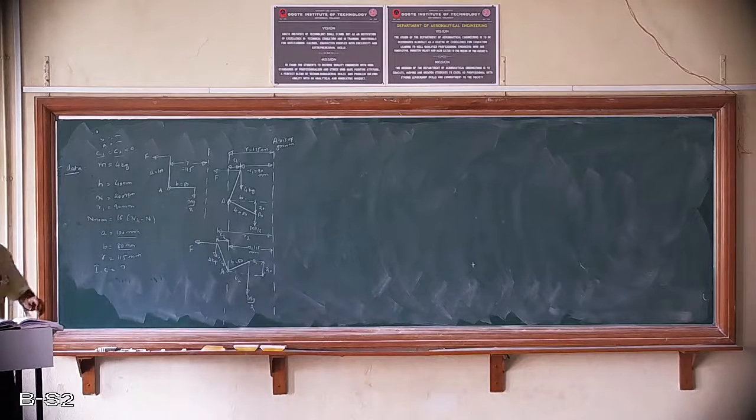Once again I will read the question, to see what we need to find out. In a spring loaded Hartnell type of governor, the mass of each ball is 4 kg and the lift of the sleeve is 40 mm. The governor begins to float at 200 rpm when the radius of the ball path is 90 mm. The mean working speed of the governor is 16 times the range of the speed when the friction is neglected.